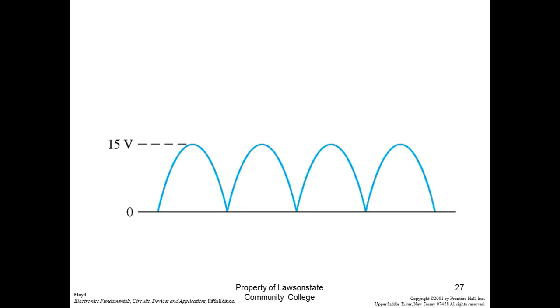So what we'd use here, if you look at your formula sheet, is V DC equal to 2 V peak over pi. What's V peak here? We don't have to use RMS. V peak is given to us. So this should be equal to 2 times 30 volts divided by 3.14. Have I lost anybody? I double V peak in my head, right? And what do we come up with?